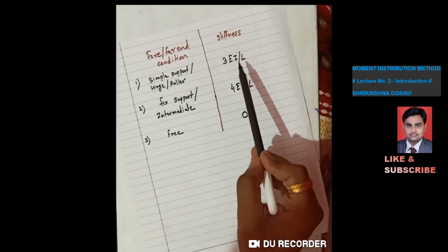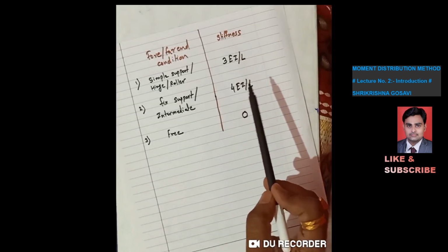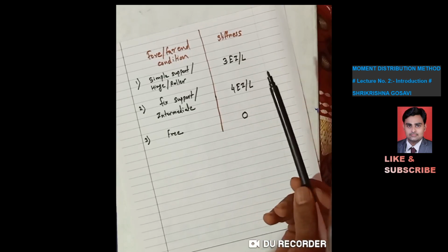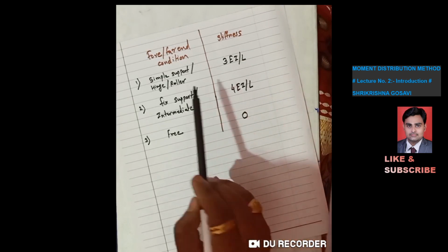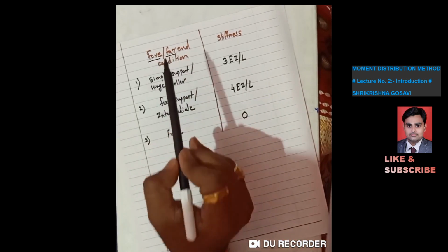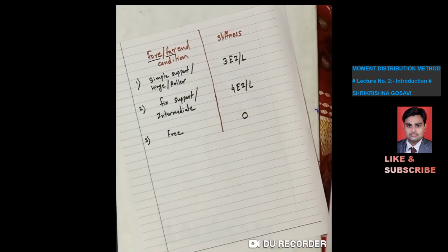This 3EI by L and 4EI by L, how does it come? This I will tell you in the next lecture, that is in lecture number 2 of the moment distribution method. For the time being, you remember this. These are the far end conditions. So far end conditions means what?